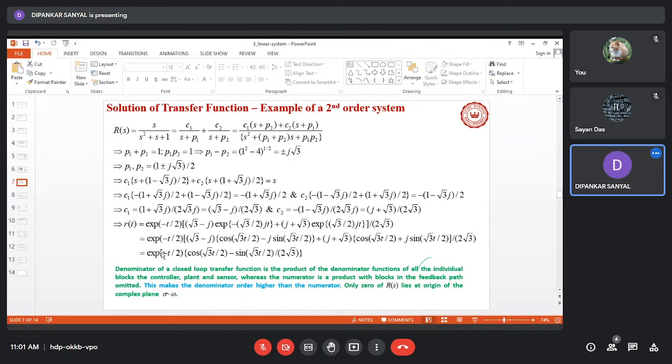So if it is the equation for error dynamics, we really require this to decay and go finally to zero or close to zero. If we do not have this exponential term, if we have only cosine and sine terms, then it implies that such a situation will arise only in case we have a complex conjugate pole pair on the imaginary axis, and in that case still the solution will remain bounded by the amplitude of these cosine and sine terms.